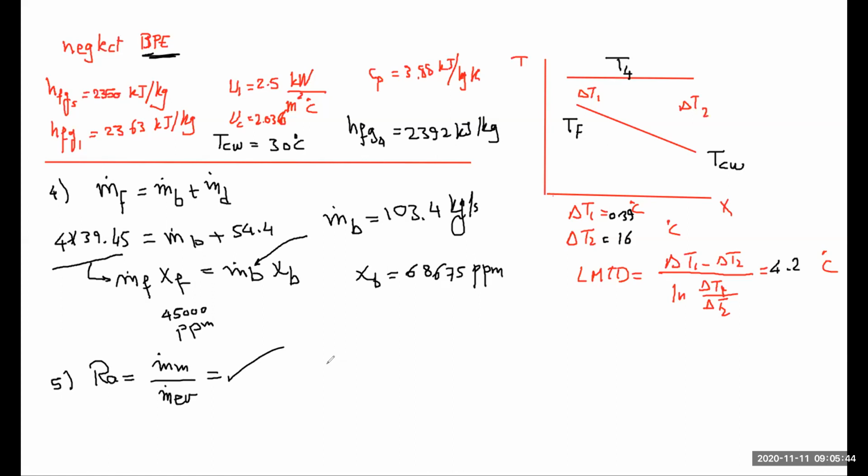What we covered right now is basically a multi-effect desalination system. Last time we solved an example of a forward feed system. Today, this is a parallel feed system, which is accompanied by an ejector or a thermovapor compressor. I can alter the problem so that the m dot entrained vapor is not given, but you know the values of the pressures so that you can calculate the entrainment ratio, which is the ratio between m dot motive and m dot entrained vapor. Then you can calculate the entrained vapor and continue the problem.